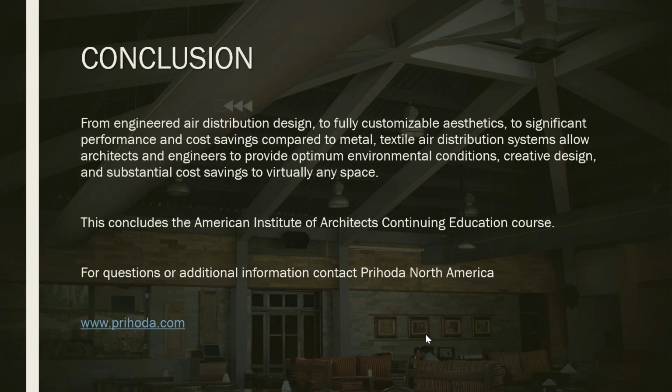You will have some pressure loss right at those transitions, but it will regain and balance out. And from the software that we use, the pressure at the inlet is also calculated for us, so we can make sure during the design stage that your air handling unit is covering that requirement.